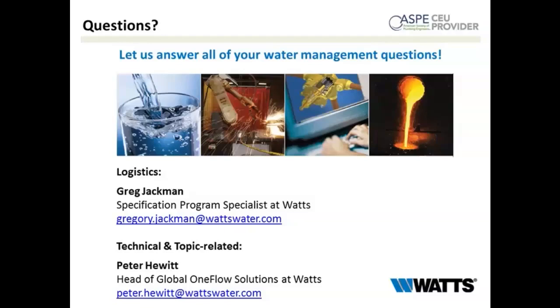Next question here. I live in an area of West Virginia that has approximately 18 to 20 grains per gallon, 308 to 342 milligrams per liter, with a traditional water softening system. Very interested in this technology. Sure. It would be applicable under those conditions. And of course, the important thing to know, if it's well water, is what is in the water. So a water quality test that identifies the elements and the conditions beyond hardness of what's in the water is important to know.